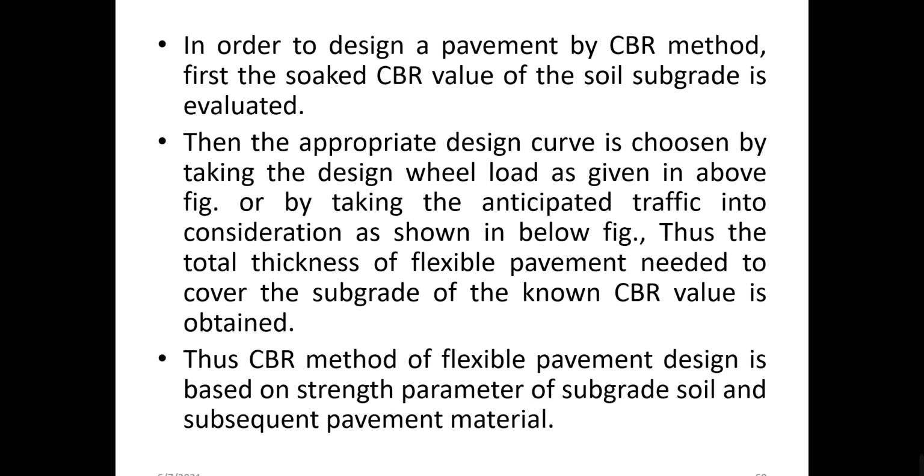Suppose the CBR of the subgrade soil is greater, but the material that you use for the construction of the pavement is very weak, then the pavement is going to fail. You are not going to blame that the CBR of the subgrade soil is weak, because it is not because of the CBR of the subgrade soil.